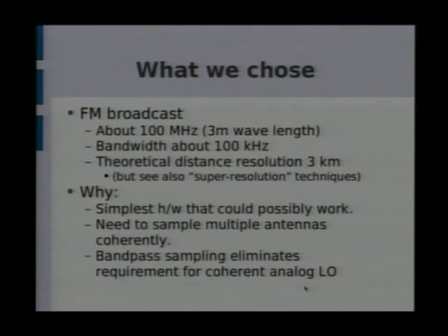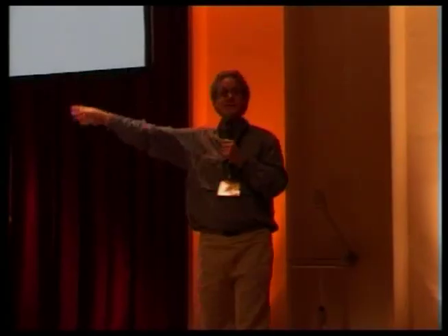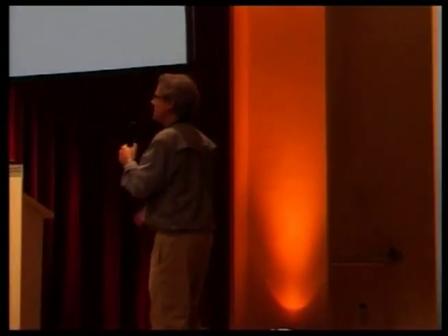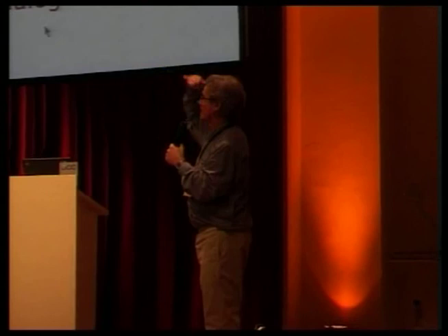So, okay, the theoretical distance resolution you get basically is the speed of light divided by the bandwidth of interest. That gives you about 3 kilometers here. So you can kind of think about this. You're getting, how do I want to say that? Anyway, trust me, that's about the answer. There's also this other technique you can Google, follow the tips in the previous talk, on super resolution techniques. There's some great academic papers on this, and this stuff's getting applied now.